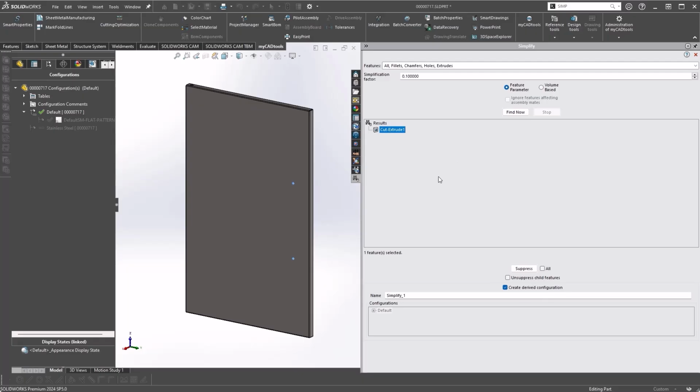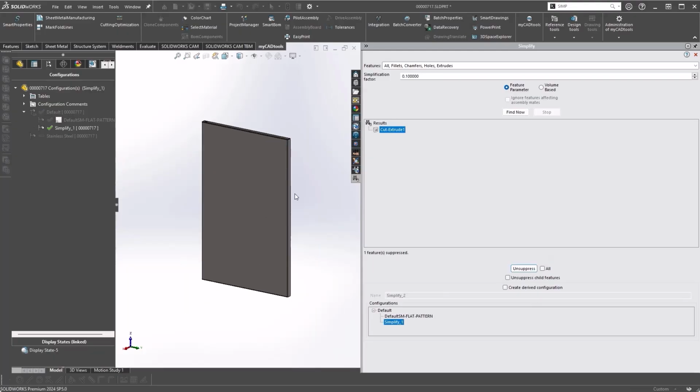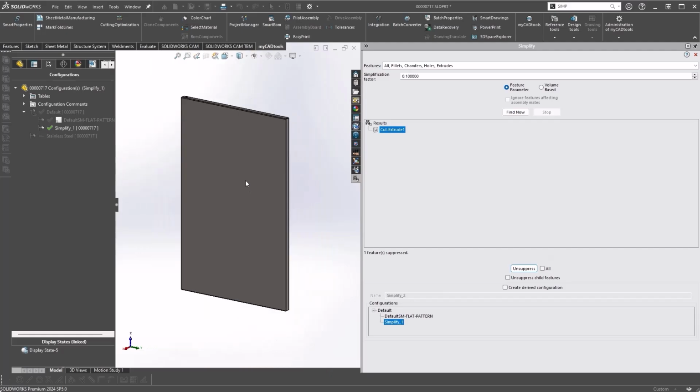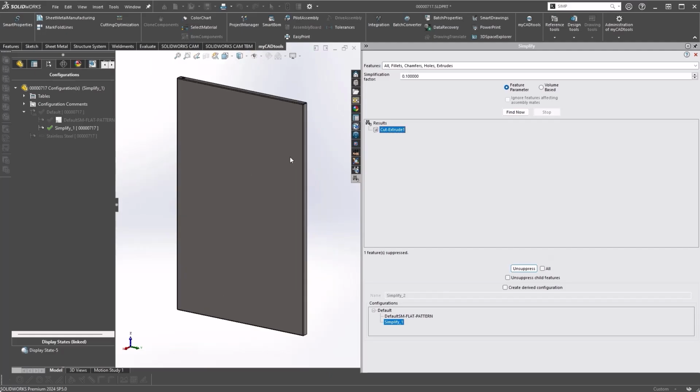Why this is important is that usually when laser cutting is being executed on a part, you might run into some flashing issues or some draft angles that might force the cut out towards the side, which will cause an inaccurate cut, especially on holes. So a process that would rather be used on those holes would be punching or drilling. Once we suppress and look at the part, it will take away those two holes that were appearing on our sheet metal part.